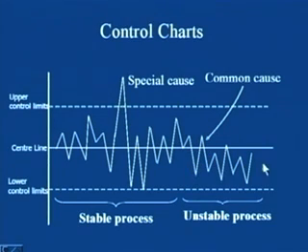So these 7, 8, 10 data points show that the average or target value of the process has been reduced. Although they are still within the limits, between the lower and upper control limits, it shows that some common causes are there, and the reason is not clearly visible.